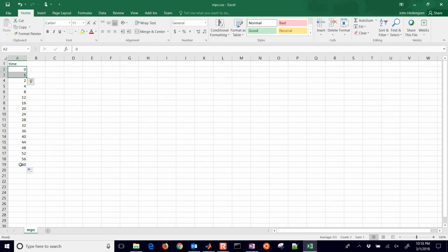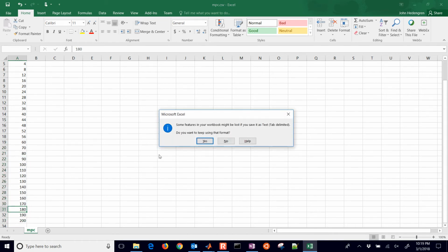That's the very first step right there. That's a very important part of our MPC controller, figuring out what our cycle time is going to be. And then we also want to figure out how far to go into the future and with what resolution, so we're able to track the dynamics and also make it to steady state. So you could add more here as well. We could go 60, 70. Let me go up just a little further. I'll go up to 200, by steps of 10 beyond 60.